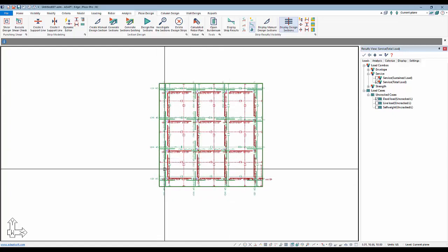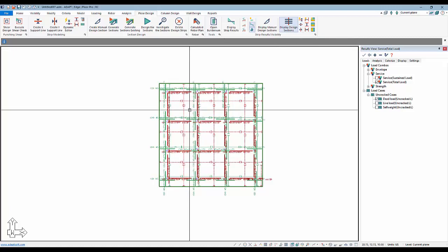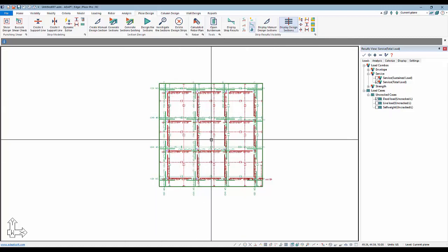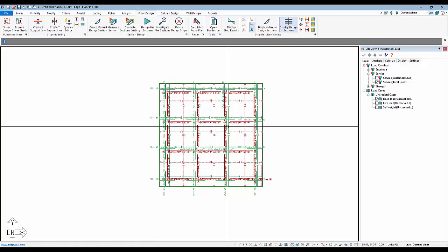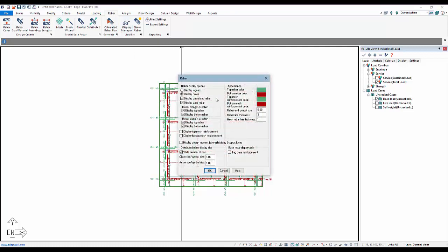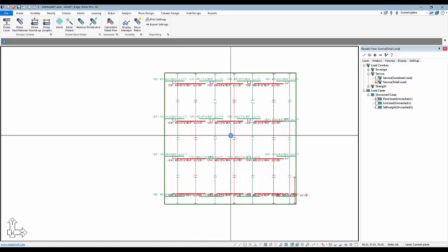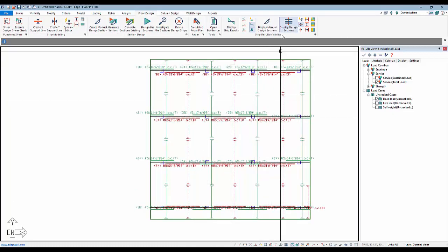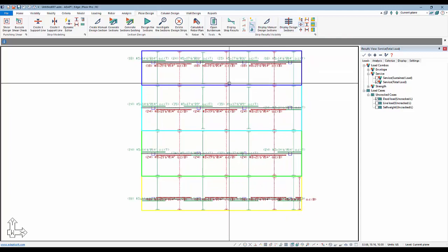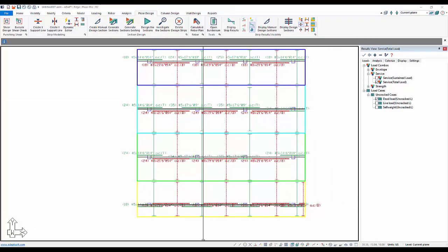And you can see there's quite a bit of rebar. We're going to focus in on just one of the strips. So I'll look at an X direction strip. Because it's symmetrical, I'll take an interior strip in the X direction. And so under rebar, I'm going to isolate under display manager the rebar in only the X direction here. Okay, and if I go back to my strips, I'll turn on the X strips. And we're going to look at this strip that you see. First interior from the top, this one here. Okay, and we have 24 number 8 bars from here to here.